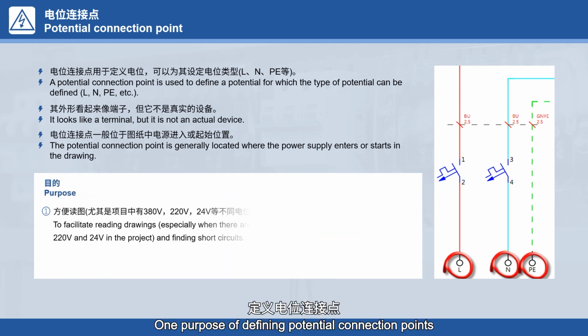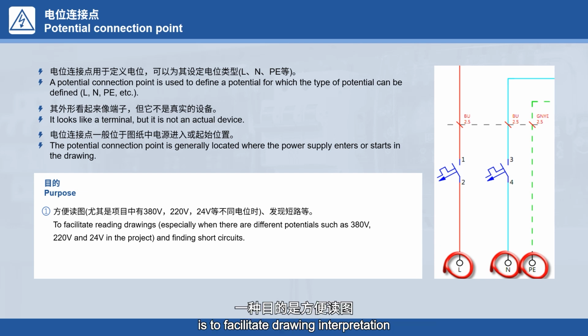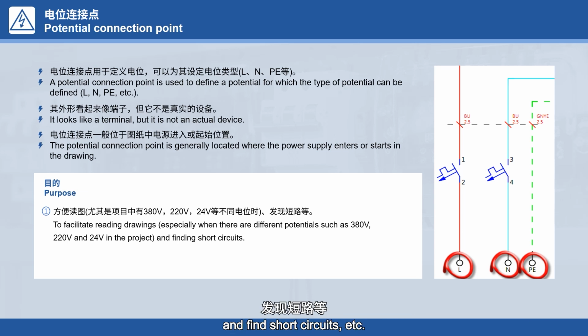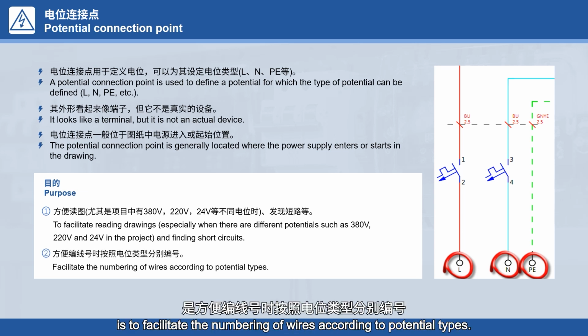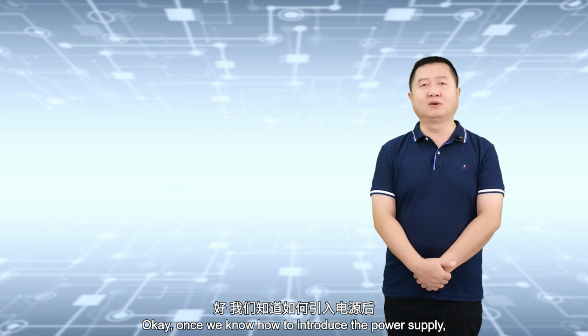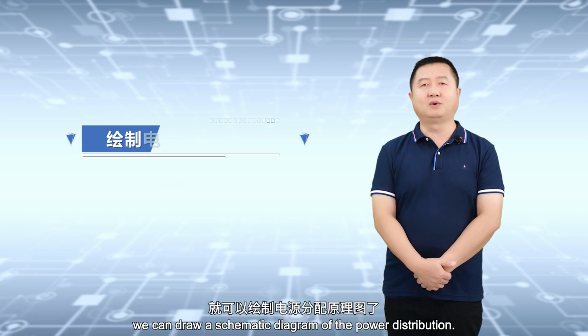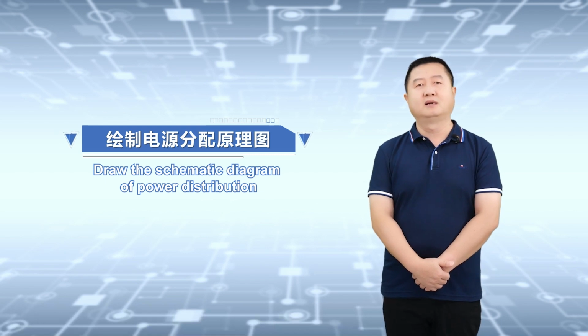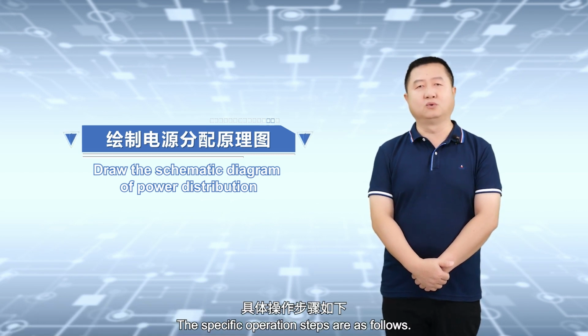One purpose of defining potential connection points is to facilitate drawing interpretation, especially when there are different potentials, such as 380 volts, 220 volts, and 24 volts in the project, and to find short circuits, etc. Another purpose is to facilitate the numbering of wires according to potential types. Okay, once we know how to introduce the power supply, we can draw a schematic diagram of the power distribution. The specific operation steps are as follows.